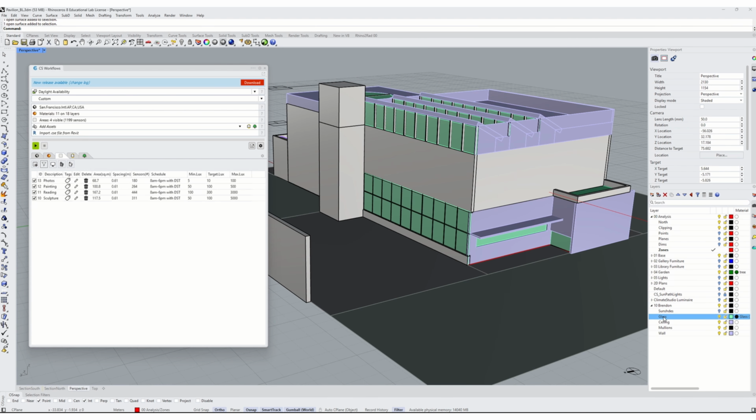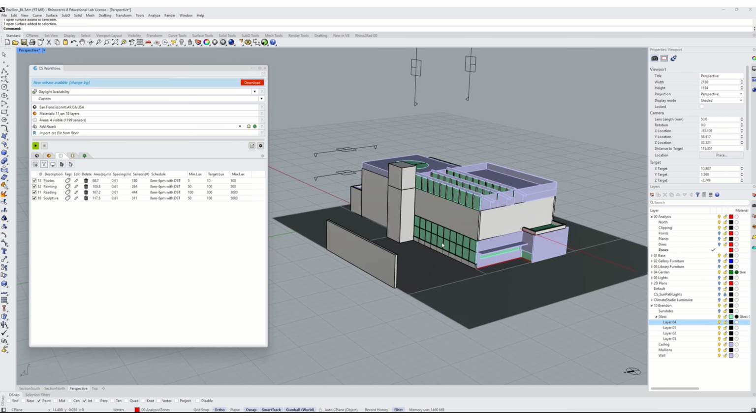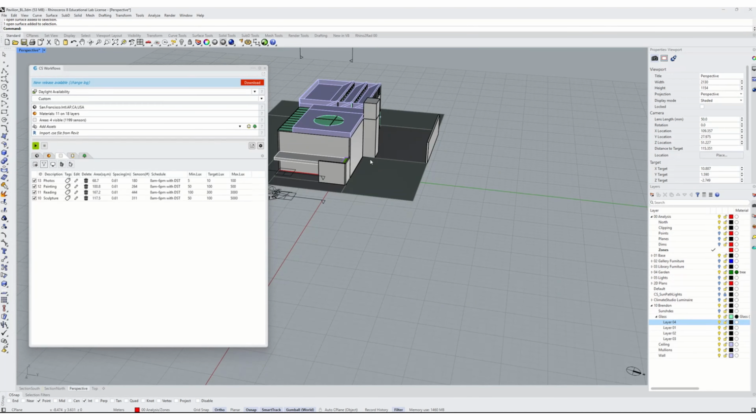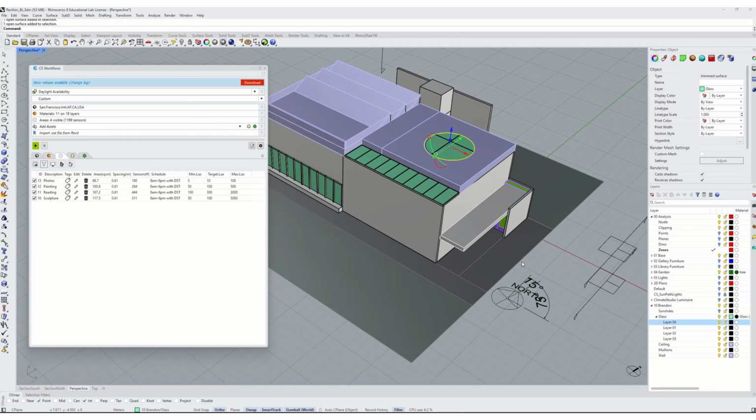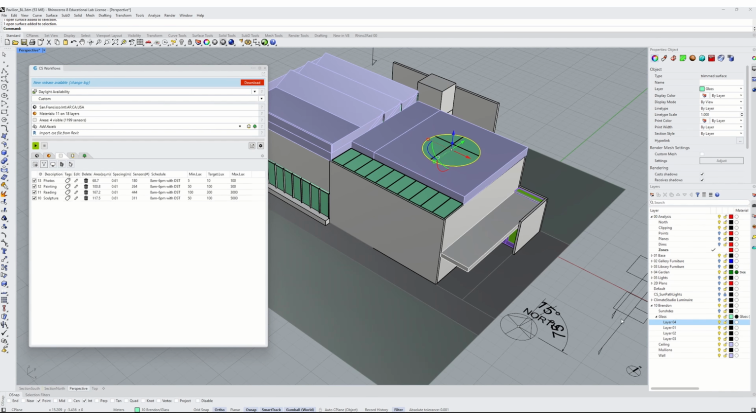And so for those, I would need to create different zones. So underneath my glass, I'm going to make a few different zones here, and you'll see as we go through it how this works out. So let's start with our skylights first. So this skylight here, I want to have the sun coming in. I don't ever want to have it with a shade on it. So I'm going to assign that to this layer, and I'm going to call that just no shade.